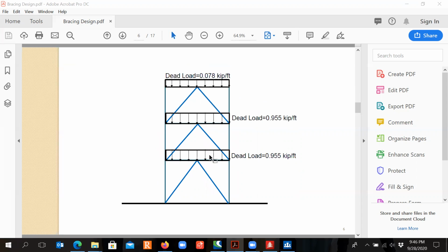And in the X direction, we have to assign the loads. For each type of load, we just do the service load. Service load is unfactored. After we input each load, we can do the load combination. Based on the tributary area, we can calculate the dead load on each beam.